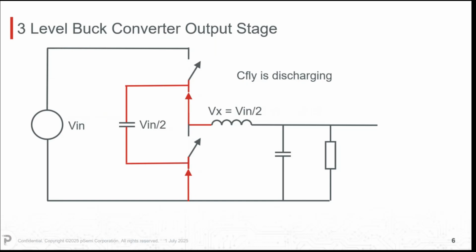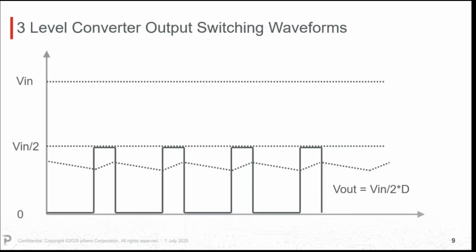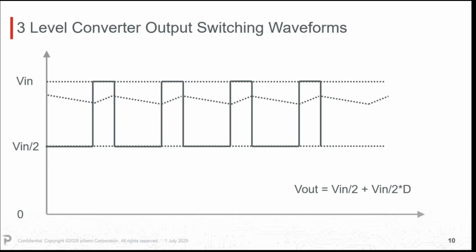As I move through these different cases, the voltage will be in a different range, Vn/2. In this case, it will also be Vn/2 of that range. The output is 0. Effectively, we end up with 2 different bands. We can either have the voltage in this band, or depending on the switch configurations, in this other band, modulating the switches appropriately to get a signal that way. So we can get anywhere within this overall range. The complicated bit is around the middle, because you're switching between the bands.